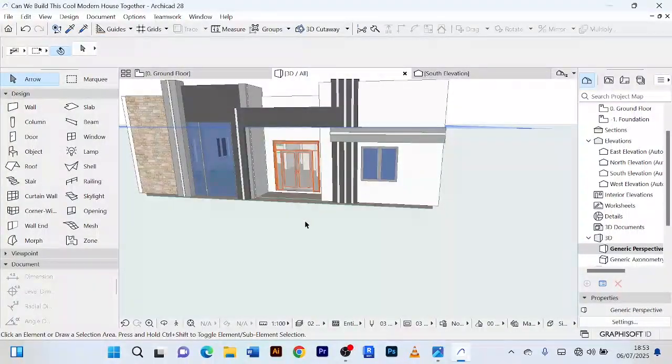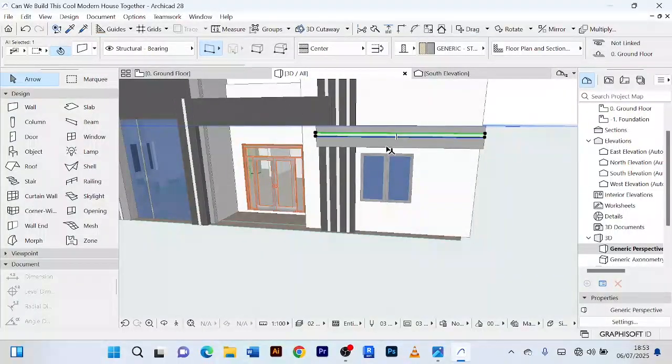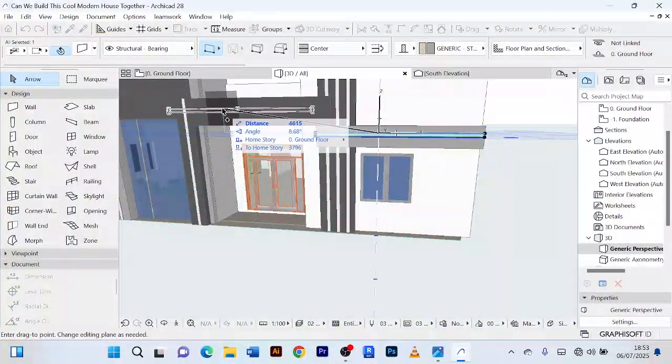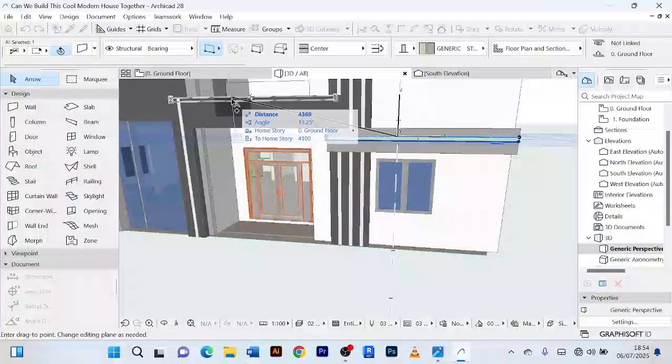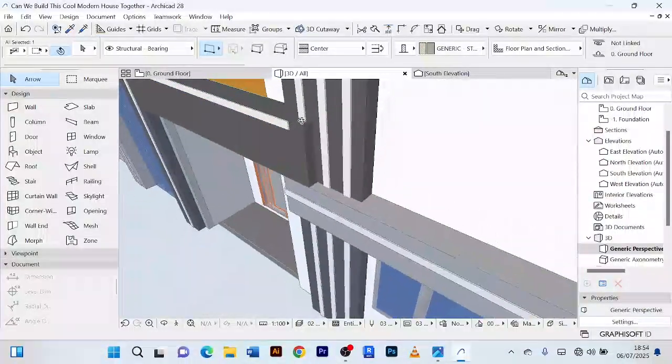And I wanted to have this kind of design also up here. Now instead of drawing it again, I'll just copy this. I'll Control Shift D. From 3D here, I'll just drag it. Now we shall fit it from here. So just pick it and put it there.